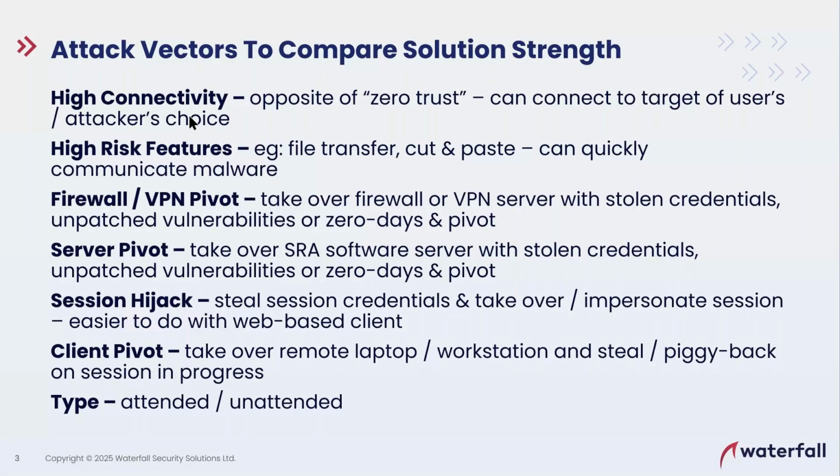Session hijacking is you've got a session in progress from the remote laptop into the OT network, and someone takes over the session and starts using the permissions of that session to attack the OT network. This is easiest to do with web-based remote access tools because 9 times out of 10, to take over the session, all you need to steal is the cookie, because that's how web servers keep track of sessions from one point to another.